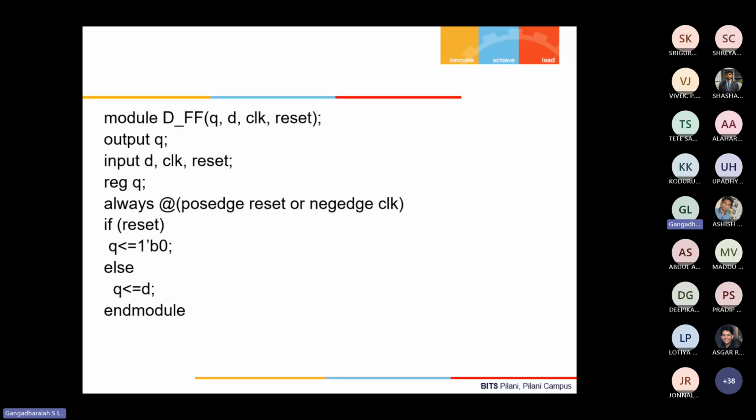When you synthesize, the kind of netlist that is really required to meet your design constraints is generated. By looking at it, a PD guy will try to place it and route a signal from one module to another, or from one cell to another. He will try to optimize so that it occupies less silicon real estate and is optimized with respect to speed. Is this clear? That PD guy will have to look at it.